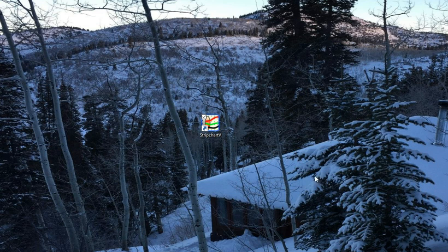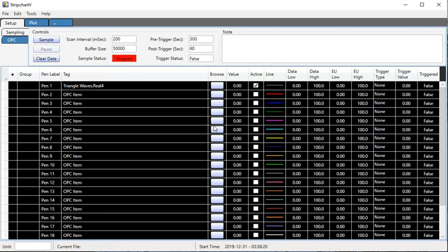This is a basic introduction to the StripchartV program. So we'll start by launching the application, and it brings up this default configuration with one pen configured. That's a simulation pen connected to a Matricon OPC server. So what we're going to do in this example is just start browsing my OPC servers, connecting to some PLC addresses, and looking at some data online.